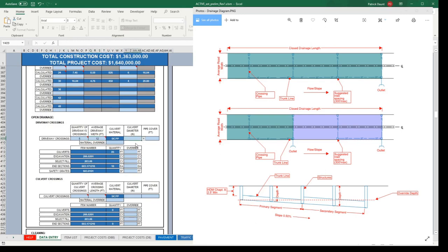It's also going to take into account, let's say we have a 2 foot, that's pretty deep driveway crossing, the culvert length coming through that slope. So if we do 1, go a little less, perfect. So 1 foot, it's basically this pipe length is taken into account at a 1-on-3 slope.